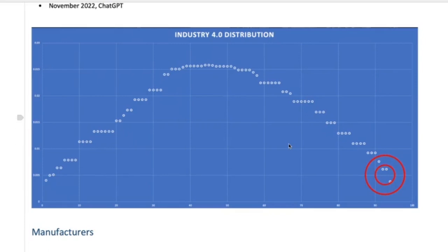Because the moment TCP/IP won, you could take all the data on the plant floor and all the data in the IT department and put them together, and you didn't have to do it over a serial network. Until 1998, you had to do it over serial. In 1998, when TCP/IP won, you could connect them together, and suddenly we had automation data and business decision-making data put together.